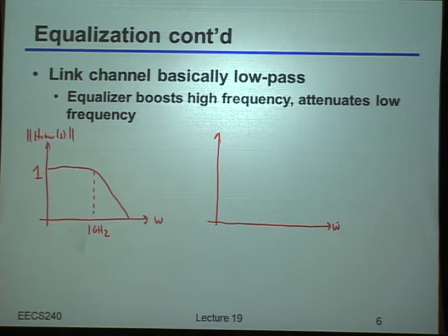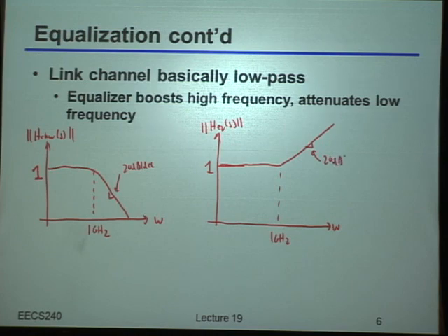Yeah, it's a high-pass filter, but more specifically, let's just say that the gain here was 1. So what would be the DC gain of that high-pass filter? And let me just call this H EQ of S. Okay, it'd also be 1. All right, so then what else? Okay, then it goes up at what frequency? 1 gigahertz. Okay, good. And let's just say that this was 20 dB per decade. Of course, this should also be 20 dB per decade.